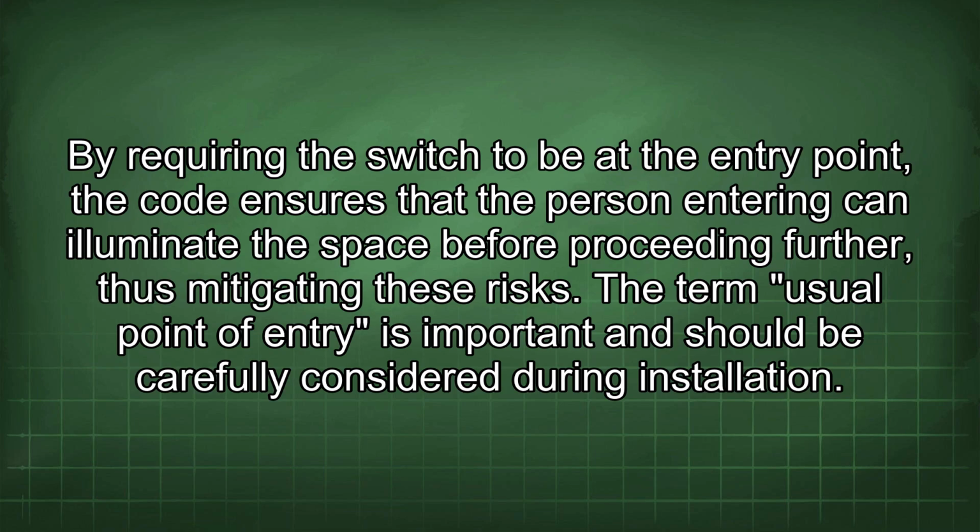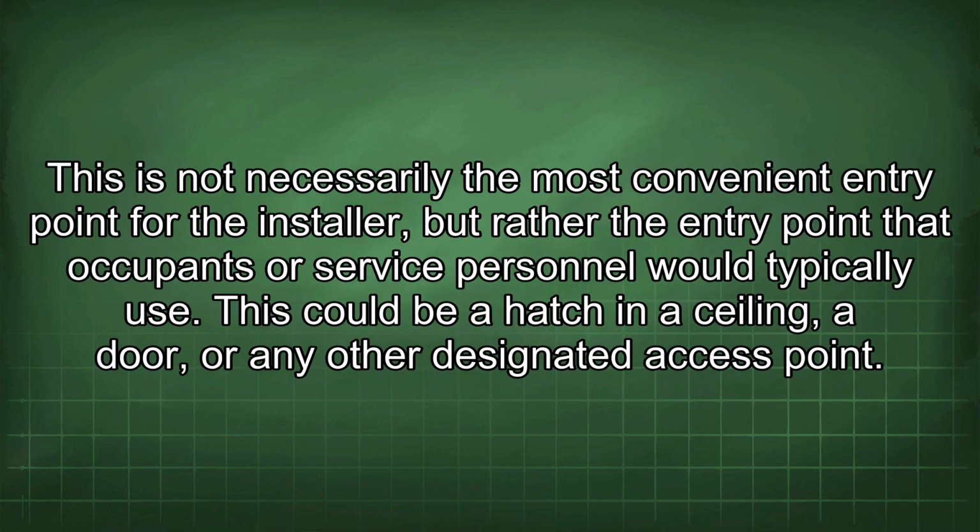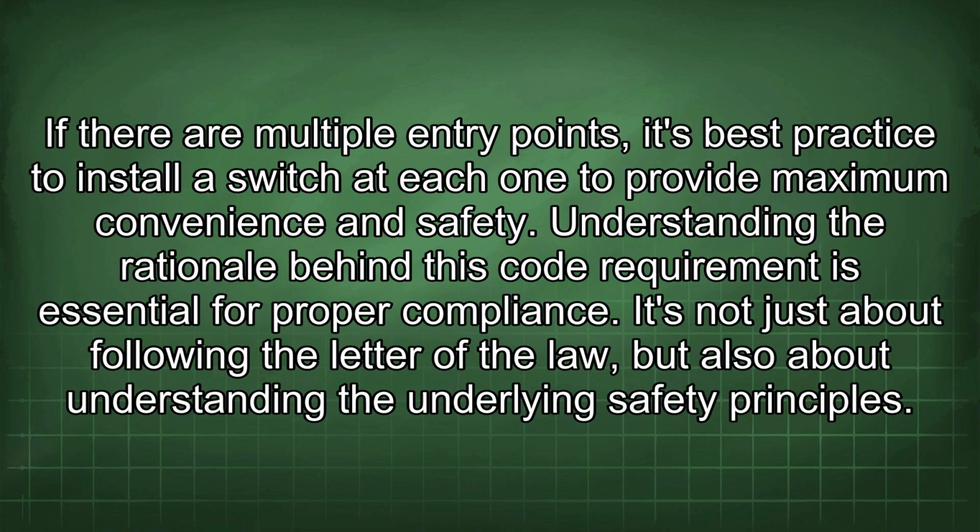The term usual point of entry is important and should be carefully considered during installation. This is not necessarily the most convenient entry point for the installer, but rather the entry point that occupants or service personnel would typically use. This could be a hatch in a ceiling, a door, or any other designated access point. If there are multiple entry points, it's best practice to install a switch at each one to provide maximum convenience and safety.